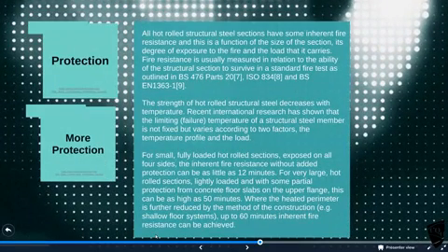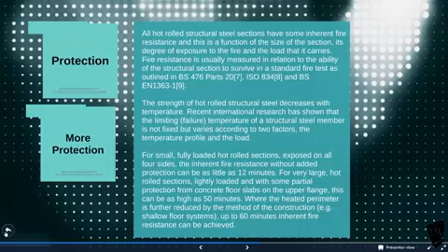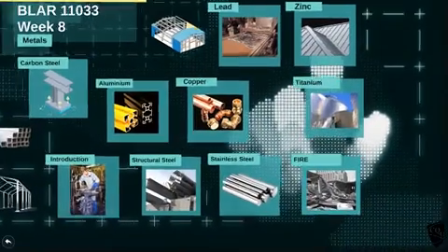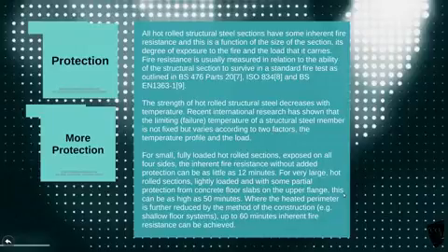So, hot-rolled structural steel in fire, what happens to them? Well, if I go back and show you, can I just get the picture? No, it melts. It melts, bends and sags. They've got a little bit of resistance, but that really relies on how big they are, how much of a cross-section they've got. Most of the ones we use haven't really got an awful lot. It's also affected by the load that's carrying them. So if they're heavily loaded, they're likely to fail in a fire.